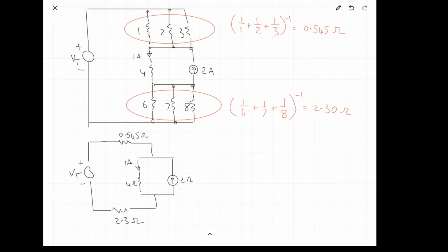So let's look at what we can actually calculate in this circuit. Using Kirchhoff's current law, we know that the current here, we remember it from before, it was 1 amp going in that direction. The way we calculated that was 0 equals, and remember we take all the outs to be positive, 1 plus this one minus 2.